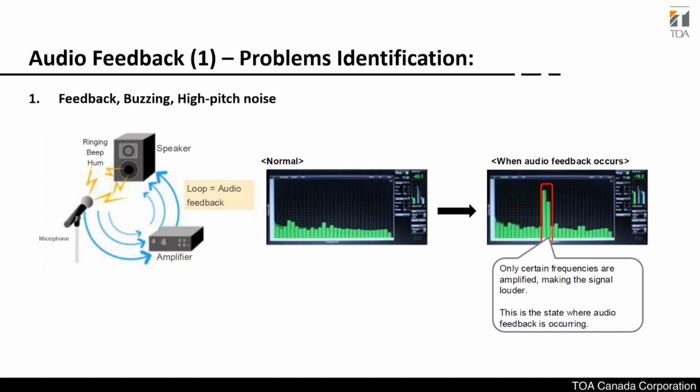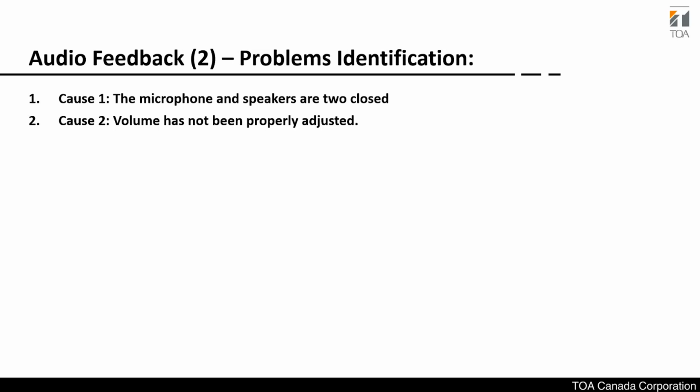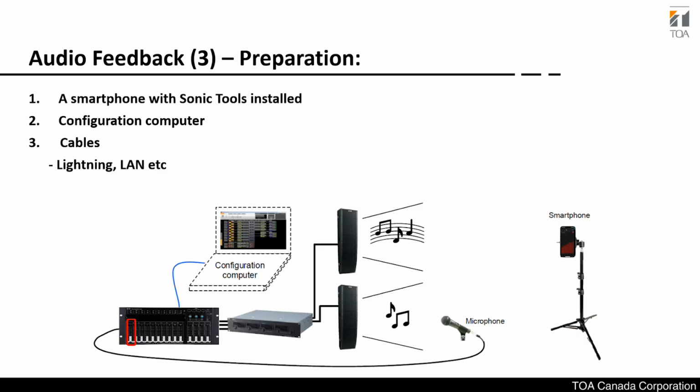So the next common issue will be audio feedback. Audio feedback, I think most of the integrators and installers experience this. Usually it's a loop of audio feedback from the system. The cause will be either that the microphone and the speakers are too close, or the volume has not been properly adjusted.